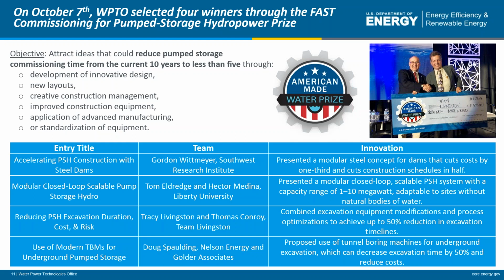Our other two winners had to do with using steel dams for constructing upper reservoirs. Steel dams is something that has not been done in the U.S. for a number of years. They have sort of revived the concept, and they really think there can be some significant cost savings for construction of reservoirs for pump storage. And then finally, a modular closed-loop scalable pump storage system that can be pretty much constructed anywhere in the country without natural bodies of water.